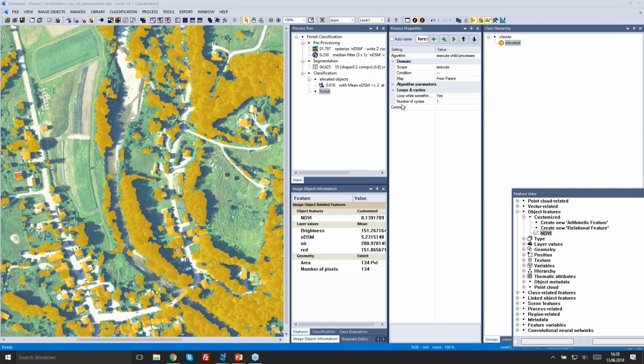One I've answered to the group already, but if anybody had missed this in the question dialogue, we had a question earlier regarding segmentation, whether it's possible to use just a single layer within segmentation, or do you always have to use multiple layers within segmentation? The answer is yes, you can base your segmentation off of purely a single layer, even within the multi-resolution segmentation algorithm, but you can also use additional segmentation algorithms available, and base them off of a single layer.